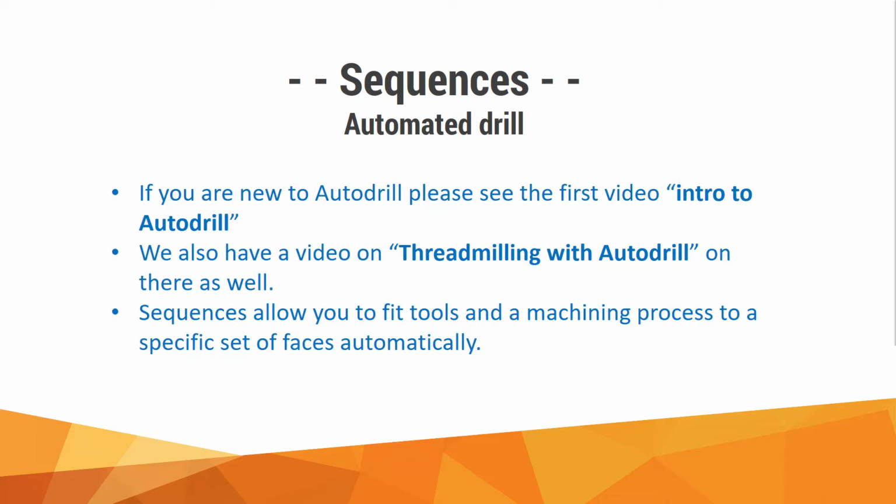Sequences allow you to fit tools and a machining process to a specific set of faces automatically. So instead of programming similar type geometry over and over and over like we do with regular drilling, this allows us to automate with a little bit of work and program incredibly fast and drill everything you need without touching all the different holes that you might have on a block.